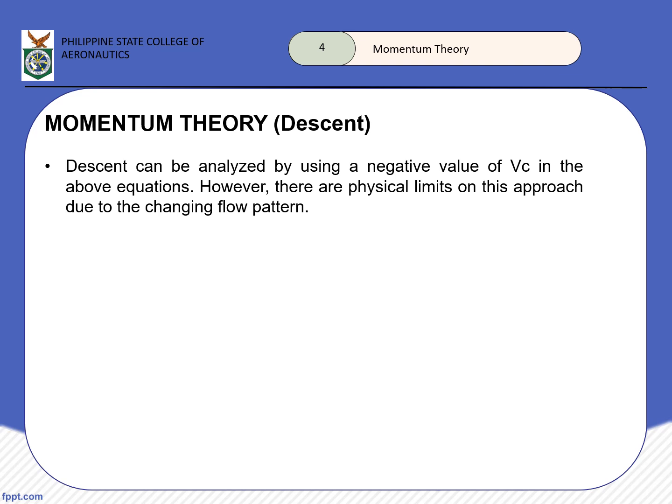So what happens? The rotor is now pretty much recirculating its own wake to create momentum change. There will come a point where, since our rotor is just recycling its own wake, we will have no change in momentum. And as we defined thrust a while ago, thrust comes from the change in momentum. So no change in momentum means no thrust.